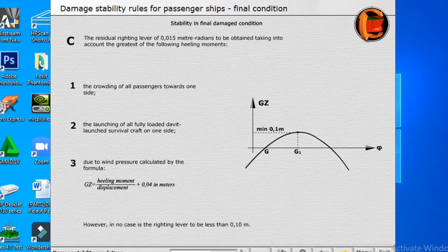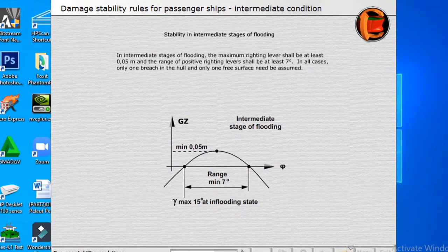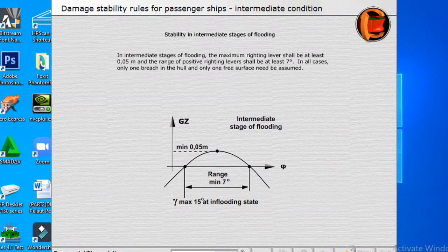National rules. The national maritime authorities of countries also define the stability of ships, through the so-called Stockholm requirements. The ro-ro ship shall, in addition to complying with the full requirements of SOLAS 90, survive with a defined amount of water on the ro-ro deck, having residual stability according to SOLAS 90. These national rules concern ro-ro passenger ships.